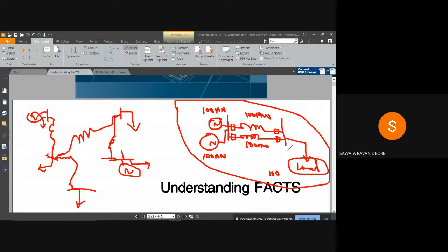But here, if you see in Kharghar city, for example, it has some ring main sort of interconnection. Means if one end of the source, for a particular distribution feeder box, if one end cable fails, the feeder can be fed from the other end.